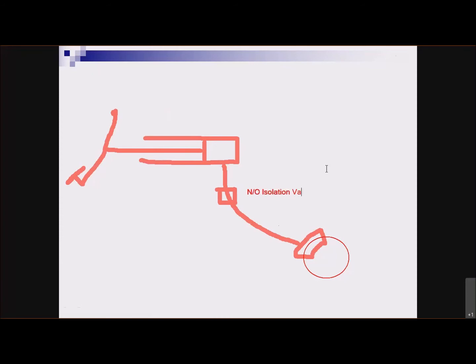Isolation valve. It's a solenoid valve. All right. Right there. So when the computer does nothing, right? Computer does absolutely nothing. That valve has no effect on the brake system. Fluid still flows through this brake line here, to the caliper, and the wheel stops.